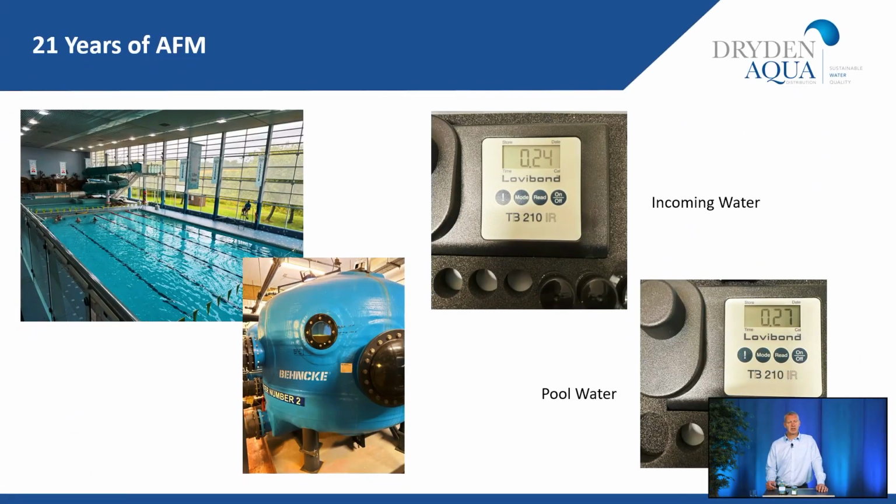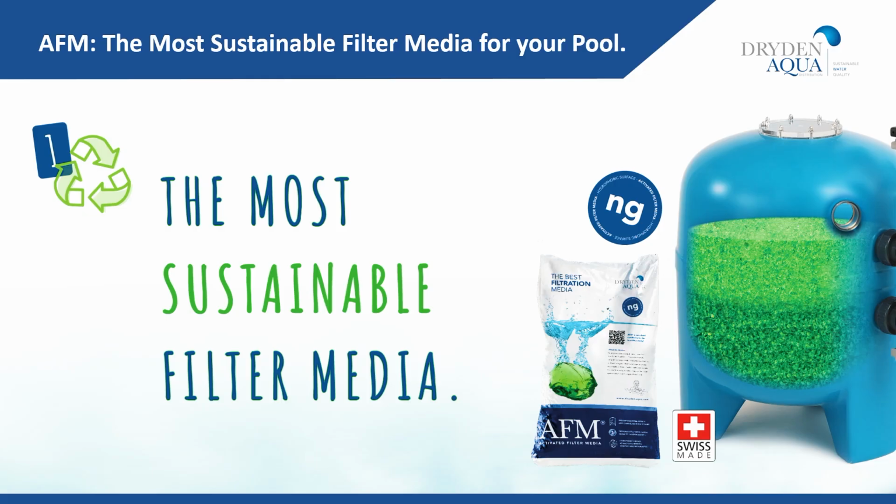Now, bearing in mind this is over 21 years now, the pool water was showing an NTU of 0.27 compared to the incoming water at 0.24. So very, very close to the quality of the incoming water. NTU is the measure of the turbidity, and the maximum acceptable level in the UK is the same as drinking water, which is 0.5. So the higher the number, the more turbid, the more cloudy the water is essentially. So the water today is just as good as it was 21 years ago. So AFM, the most sustainable filter media for your pool.